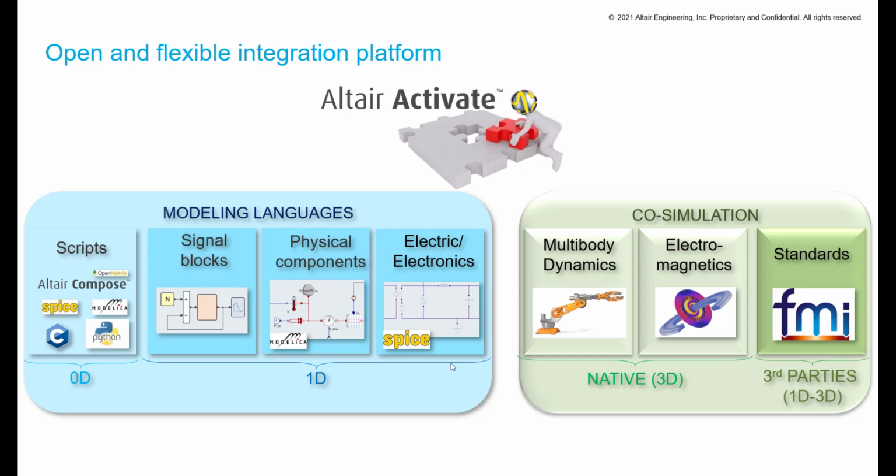You can co-simulate with any outside third-party tool that embraces the functional mockup interface. So any other third-party tool with which you could export a functional mockup unit or a subsystem, you can bring in that functional mockup unit into Activate and co-simulate with that subsystem as well.